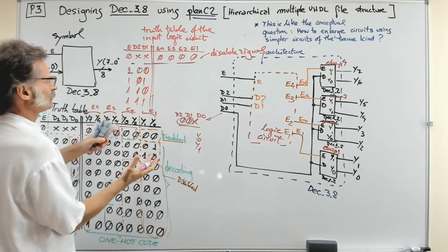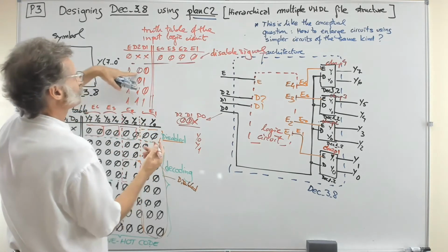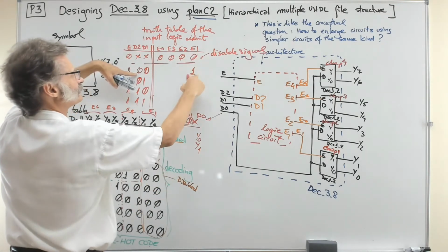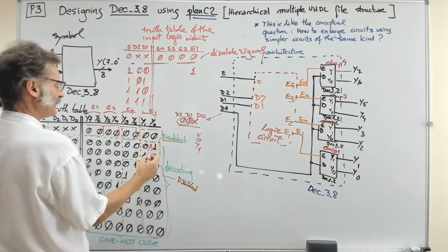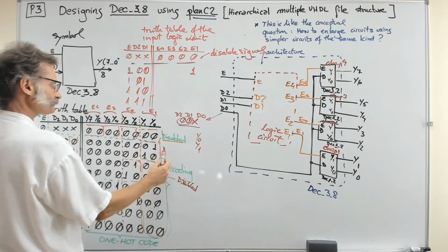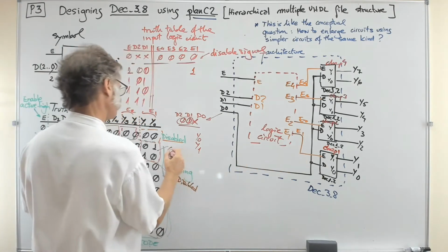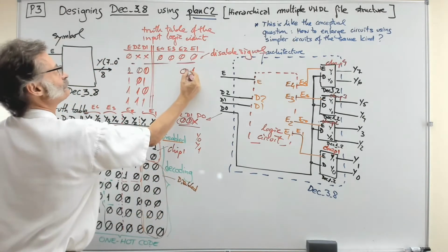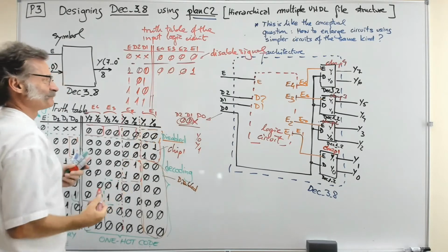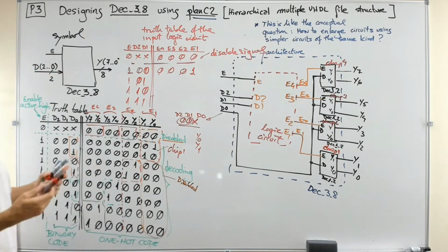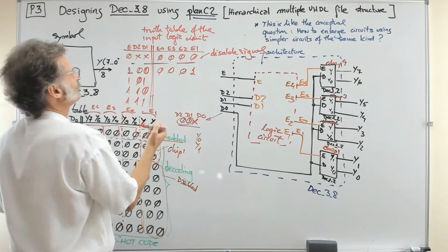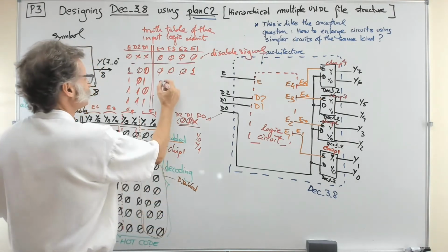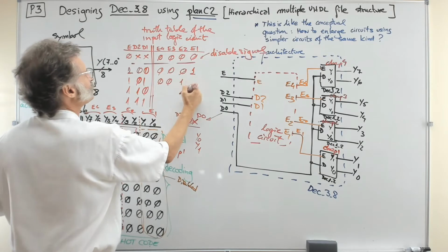So 0, 0 is for activating the E1, because the E1 will allow this chip, the chip 1, to go on while keeping the others disabled as if you had input E equals 0. But that's the idea. So now you only have to go doing the same.